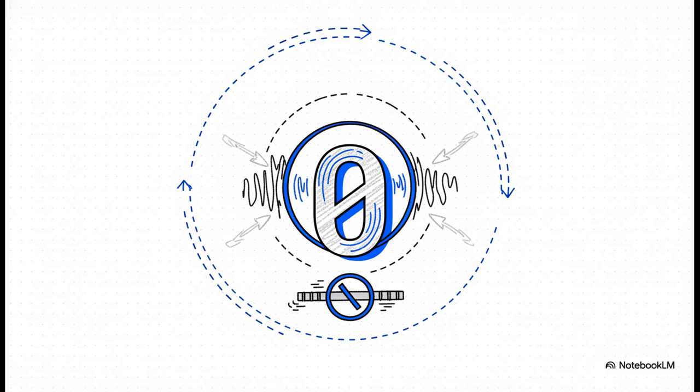Let's look at the mathematical extremes for a second, starting with S equals 0. If slip is 0, the rotor is running at perfect synchronous speed. But, as we just learned, that means no flux lines are being cut, absolutely no torque is produced, and the motor fundamentally fails its objective. It just coasts along until it slows down again.